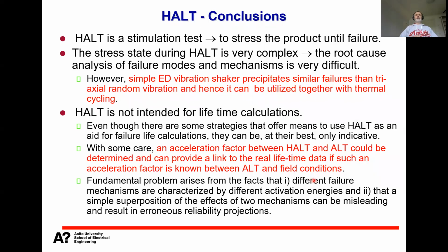And now we could kind of conclude, okay, what have we learned from the basic HALT process. So what is the idea? And then also what kind of tools you need. So first of all, HALT is a simulation test. So the purpose is to stress the product until the failure, and you don't consider that much the relevance of those stresses. So you can overstress.